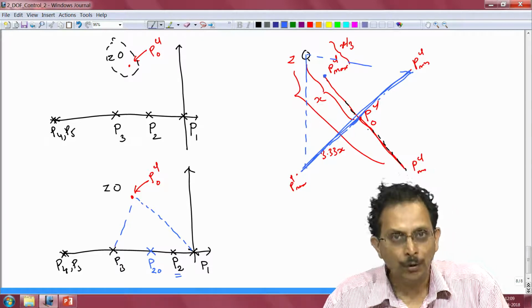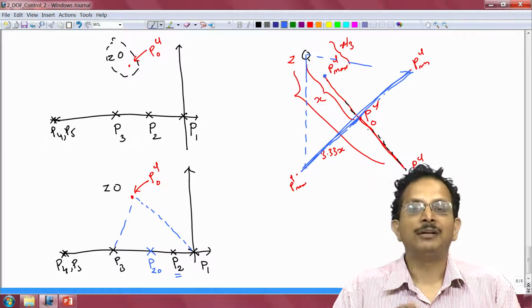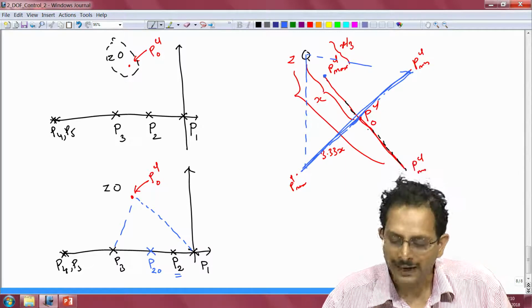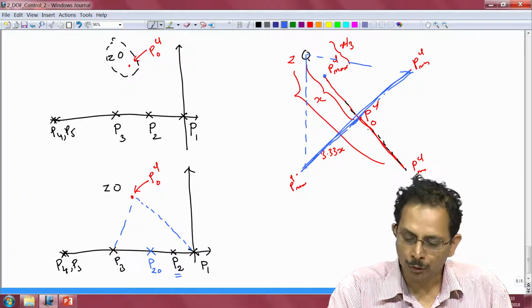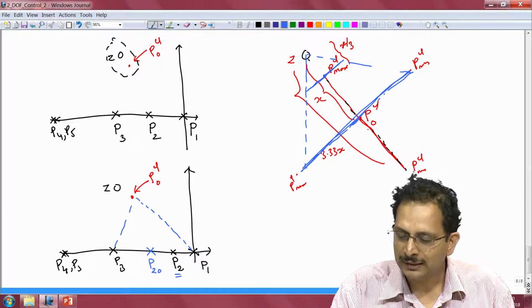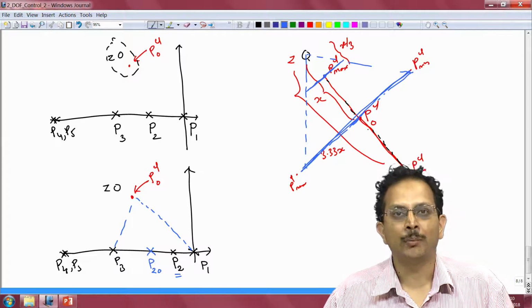Now suppose the gain is at its maximum value and we allow for uncertainty in the position of the pole of the plant, then we know that the closed loop pole is going to vary along a straight line of this kind, which is going to be parallel to the straight line along which it varied when the plant's gain was at its nominal value.